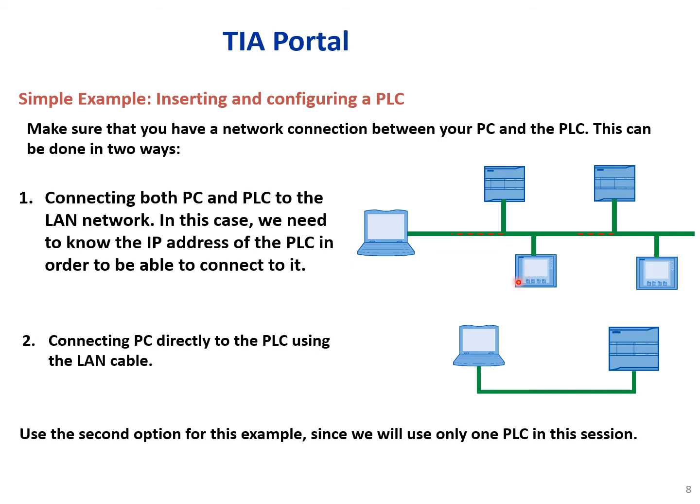And what we did, we connected all of these through a switch and with the LAN network to our PC. So we need to know the IP address of the PLC or HMI panels in order to communicate with them, and in order to know exactly which program belongs to which PLC and what actions belong to which device.